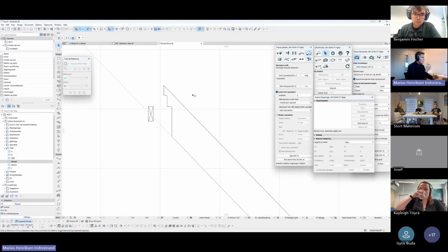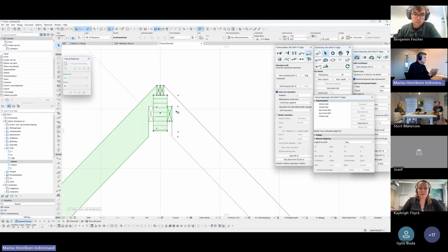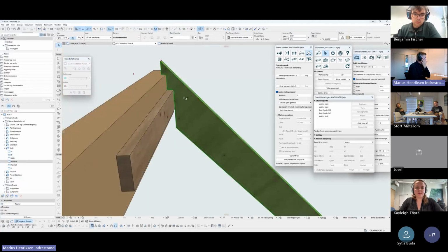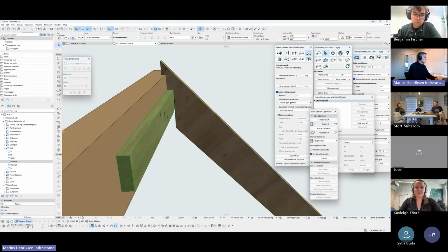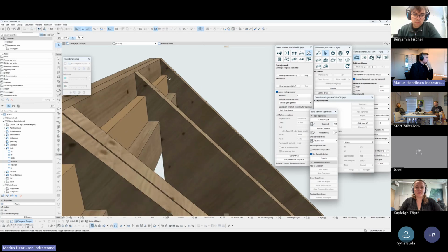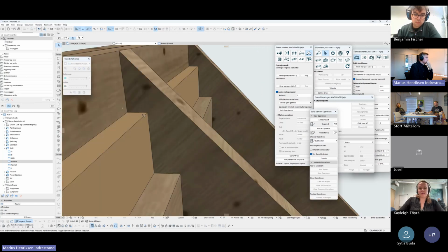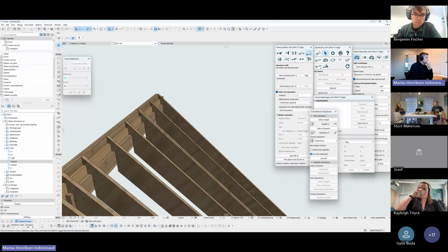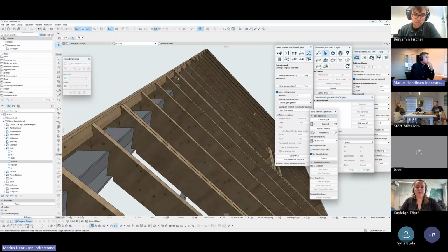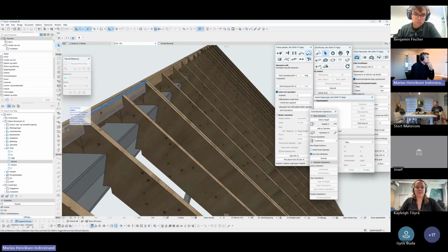So at least if you're unsure or testing some new stuff, I would advise to check it in SpeedCut. I could have fixed this model probably with solid element operations to have it perfectly made, but nobody sees this little rounding, and if they do, good job. So that was quite a bit on the VCut, but something to think about when diving into exporting to the Hundegger.